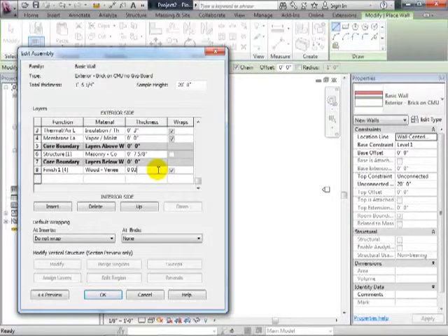Wait, how did you get that? Okay, so which one? Oh, with layers? Yeah, with the material. It's right next to it. It's the thing that says material. Okay, there's finish one, and there's material. And if you choose that, it's that little dot, dot, dot. That'll let you choose the materials. It'll pop up the whole big material dialog. And we can even create new materials if there's not something we want in there.